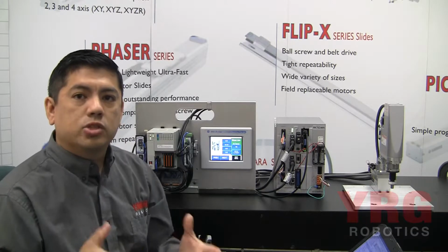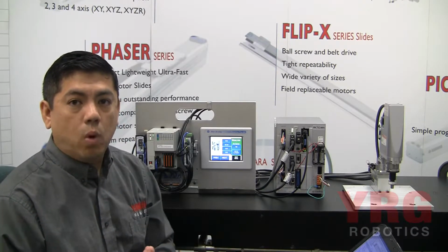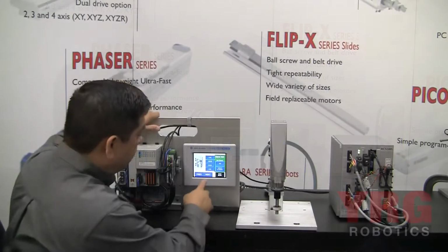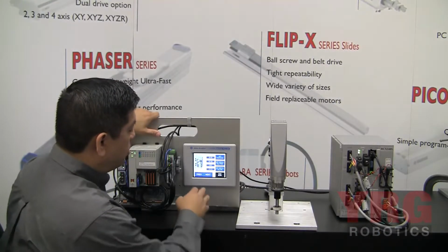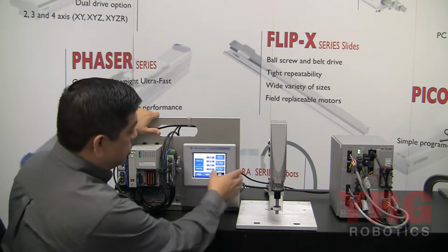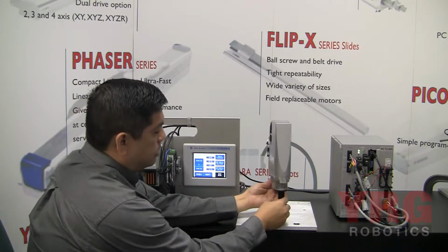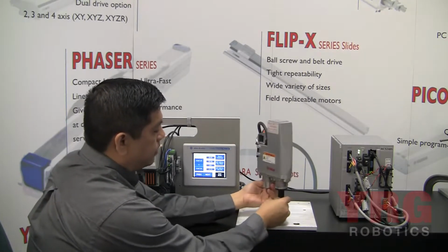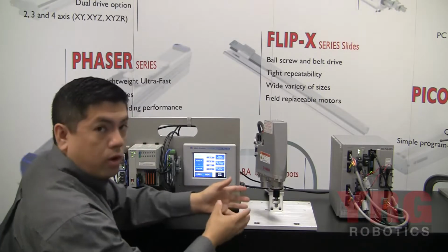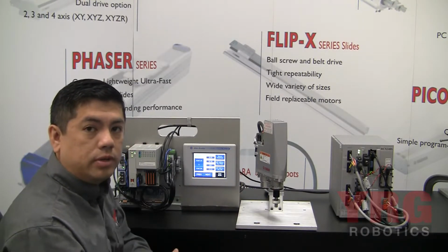Rather than storing the points in the robot controller, we can actually create points in our PLC. I've got a screen set up here where I can do remote teaching of our robot. I'm going to turn the servo motors off on our little SCARA, and now that allows us to move it freely by hand. We can also grab the values from the robot and store them into registers in the PLC.